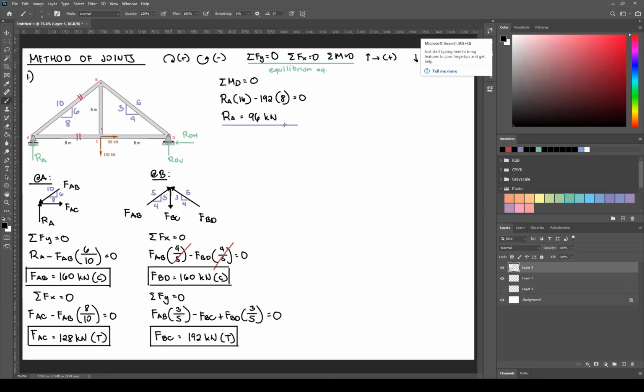Okay po, ma'am. Thank you po. Okay, no problem. And again, for method of joints, when we have the same force that we solved for earlier, you're copying whether it's compression or tension, not the literal direction itself. So again, FAB, towards the joint, that means compression. Correct assumption.